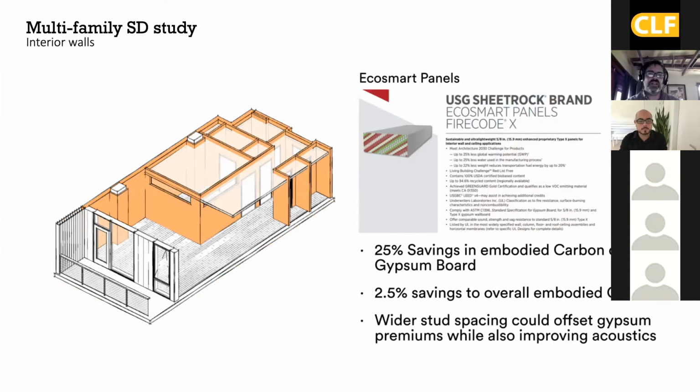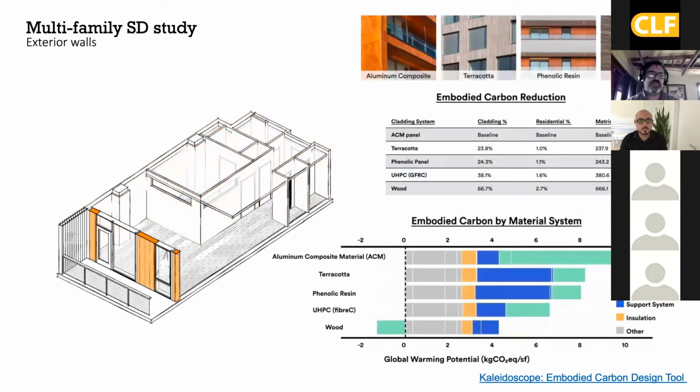If you go to the next slide. We also looked in Tally, looking at different envelope options. Ultimately, we ended up using a tool that PAE has developed that's online, it's free, it's called Kaleidoscope. So this is to say, again, whole building LCA is really important, but sometimes these quicker tools allowed us to pick 5 different options that we were looking at and get a good sense of not even just the relative carbon impact of them, but also what was driving that specific carbon impact, and to understand how we might even be able to improve that. So we're working with that right now.